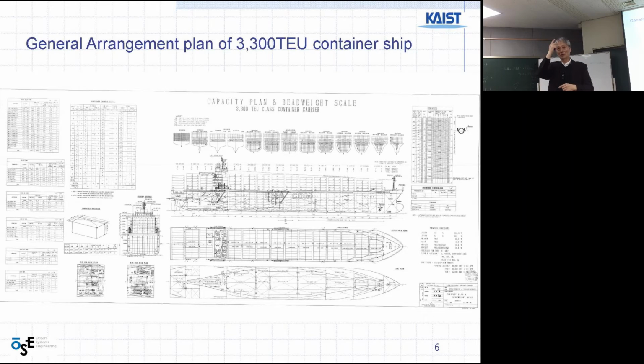And another one is stability. Stability means heavy down is good, better for stability. Because usually container ships are high in stacking, with more cargo, it can be less stable because the center of gravity is going up. So heavy containers should be placed low.